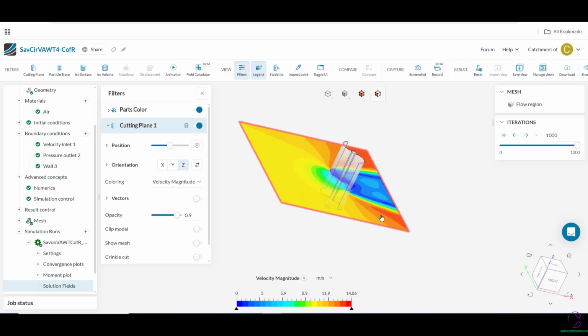From this you'll be able to understand where the wind is going to be largest behind the VAWTs, so that you can then test it in the field or in the wind tunnel to validate what has been done in CFD. You should be getting similar values compared to the CFD. That's what I explained at the beginning of this video.